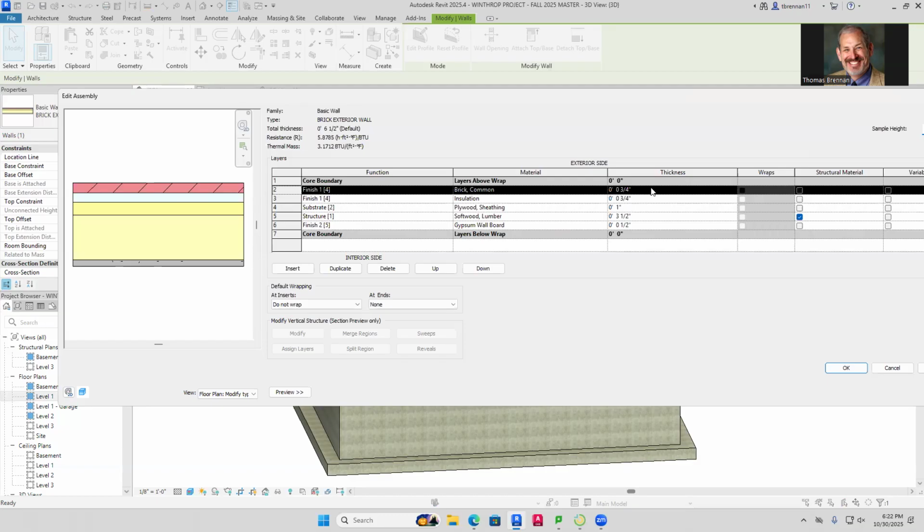Insulation is 3/4 of an inch, which is this part right here, this blue foam insulation. So the brick actually snapped into it. We talked about this earlier. And then the next item here is plywood sheathing. So you've got the plywood sheathing here, which is actually this right here. That's plywood sheathing, and that's your outside.